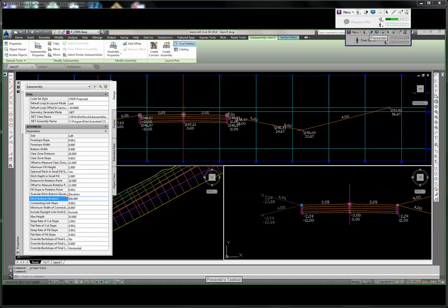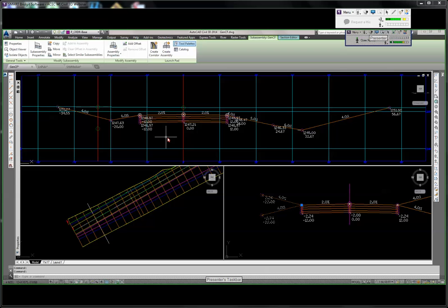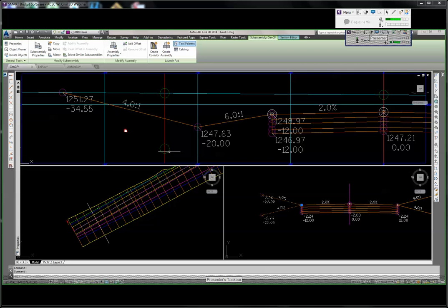If I click the override ditch bottom elevation again and choose profile, this is going to allow me to identify a profile that's identifying the elevation of the bottom of the ditch. Now, in my file here, I happen to have an alignment already out there and a profile already built. I'm going to zoom in on my view edit section here, and you'll see the red line indicates where the alignment is located. The green circle at the bottom is actually indicating where the proposed profile for that ditch bottom is located.